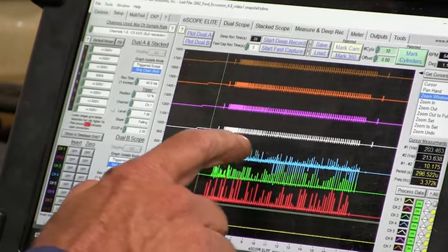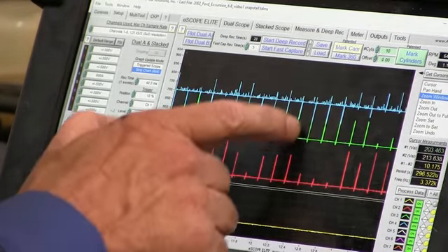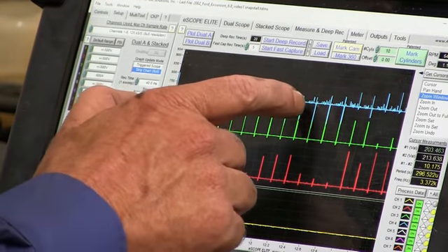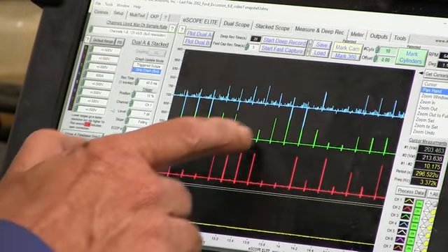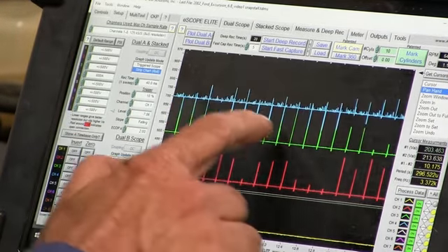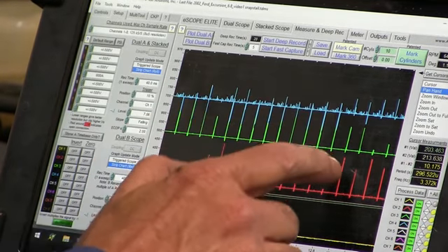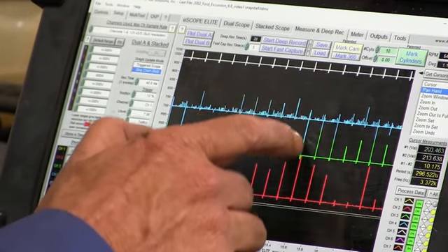And again, you can see these big coil strikes that are aligning right with the number 9 coil. And that's the amp clamp around the battery cable, the battery negative cable. And we can see that it lines up. Notice how all the big blue strikes are only lining up with the number 9 coil, not with the other coil strikes. That's because that number 9 coil is bad.